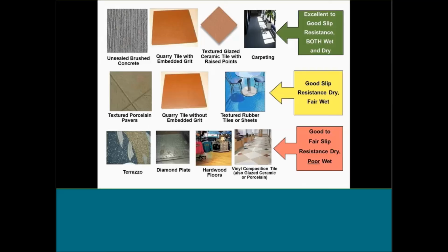As you can see here, not all flooring is created equal, and some products perform differently in terms of slipperiness. If you have a floor that you expect to be exposed to wet conditions, like at entrances or in manufacturing operations where water or contaminants are present like oil, grease, dust, etc., you might consider a product that will perform well from a slip-resistant standpoint. For certain flooring, it is good to overcompensate and try using entrance mat strategies and housekeeping to keep floors clean and dry. You might also be talking about treatment interventions, which we will talk about in a minute.